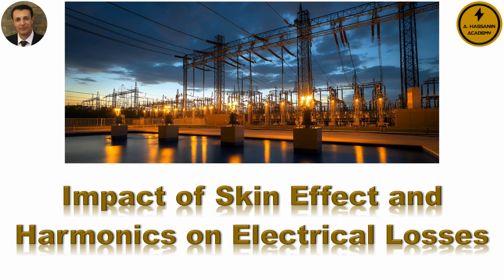is the overheating of electrical equipment such as transformers and cables, in addition to the high temperature experienced by various devices and loads such as electric motors. In some cases, these harmonics can ultimately lead to the complete failure of transformers and motors. Unfortunately, many engineers observe that electrical equipment is operating at extremely high temperatures, but are completely unaware of the role and danger of the skin effect when harmonics are present.